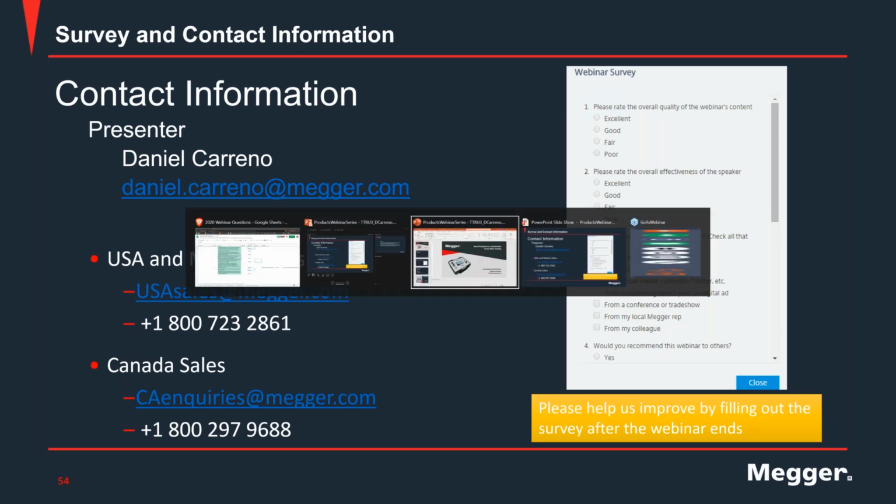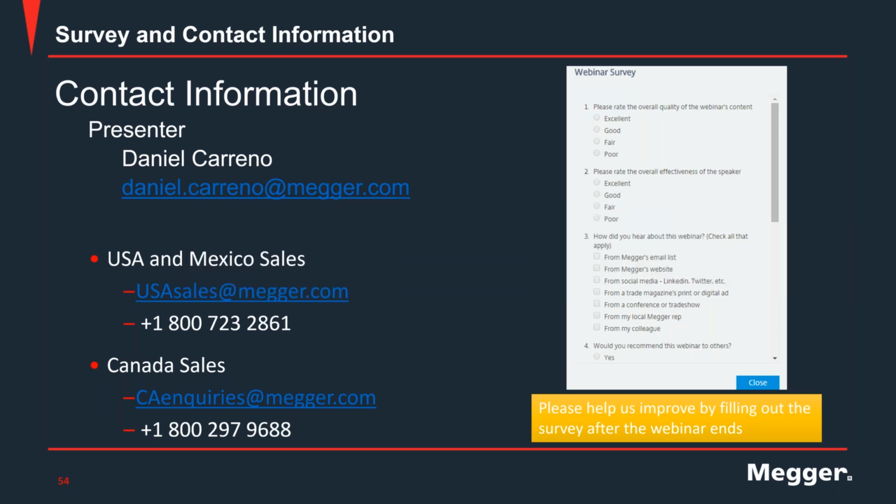Okay, to answer the question, the TTR test is considered a routine test going by the IEEE standard, which is IEEE C57.12.00, and that's the standard for the general requirements for liquid immersed distribution, power and regulating transformers. That standard lists the TTR test as a routine test, which means that the manufacturer needs to do this on every transformer, and the ratio values need to be as per the design specifications. So yes, if it's a routine test, the customer should be able to get these results from the manufacturer.